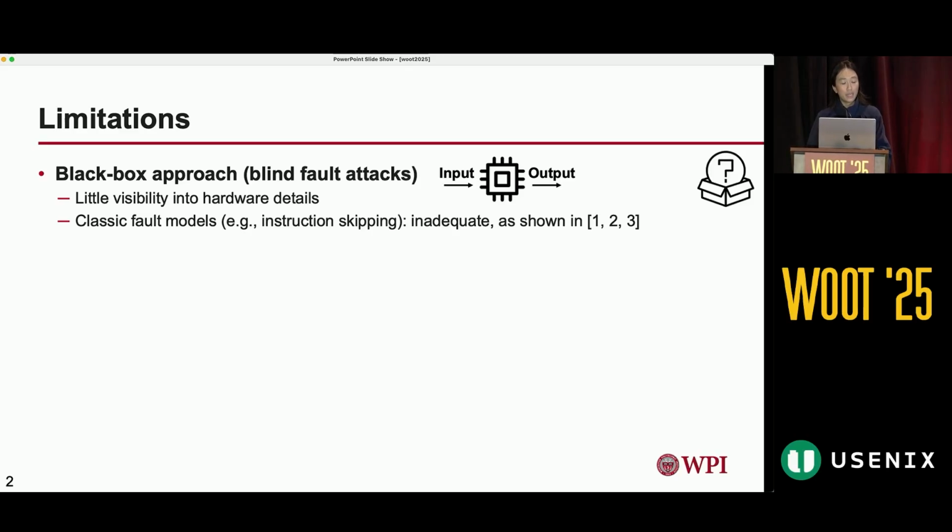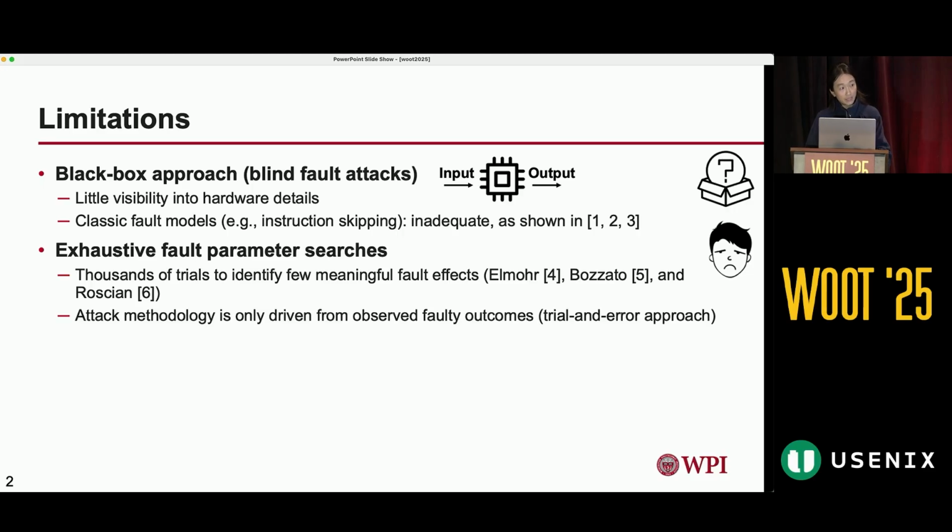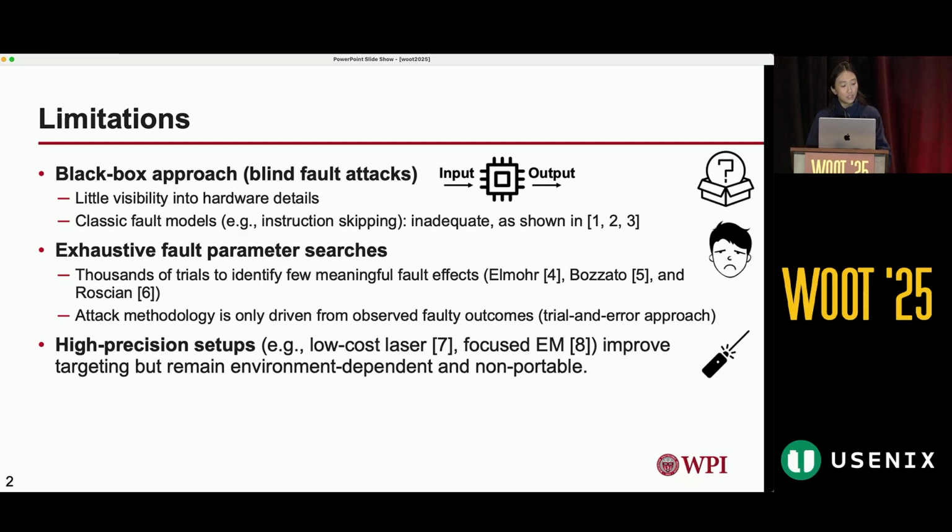People also use gate level modeling or microarchitecture level modeling. Also, because we're doing blind attacks, we need exhaustive fault parameter searches, such as thousands of trials to identify just a very few meaningful fault effects. And also, very importantly, these attack methodologies are driven by your results. Therefore, it's based on a trial and error approach, which is very difficult to conclude from, and it's not easy to make portable. Of course, there are high-precision attack setups, such as low-cost laser or focused EM. It improves targeting, but still remains environment-dependent and non-portable.